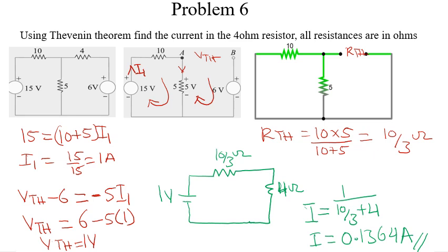Basically these are some tips you will need. With Thevenin, after solving it, you have to reproduce the Thevenin equivalent circuit, and after that, you can find the current required. Sometimes when you are having issues with solving VTH first, I advise you can solve RTH first, because it will give you a fair idea, then you come and solve VTH. You see that it's really simple.